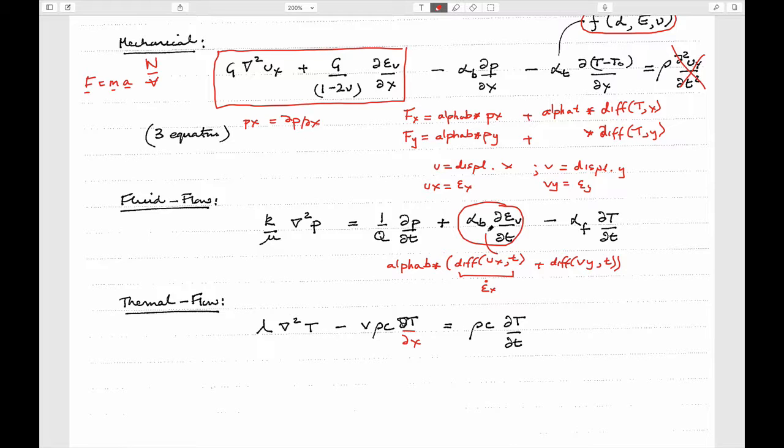If you keep the porous medium rigid and you change the fluid pressure, if you drop the fluid pressure, the fluid expands and it overflows. That's what this term is. What happens if you keep the pressure and strain both constant, it's the changes we're interested in, but you heat it up? If you heat it up, it expands. And so this term here would be, by definition, the change in volume of the fluid as it changes temperature. And so how much fluid is produced as you change the temperature over some increment of time.